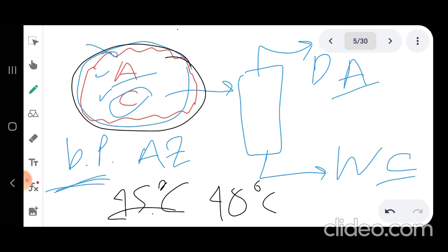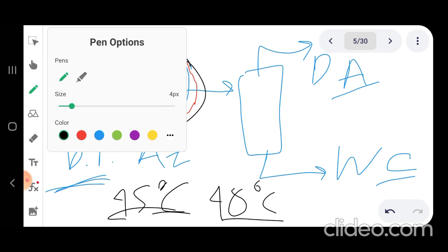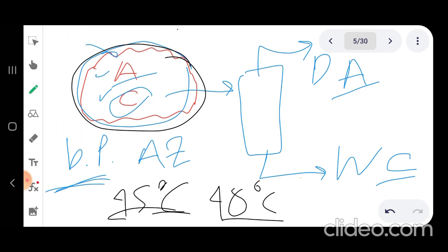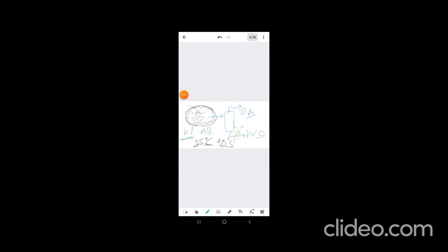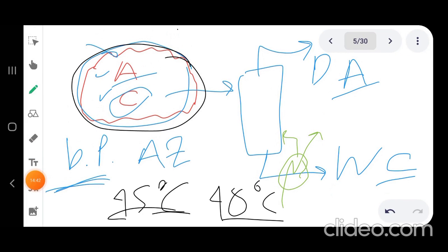These are very close, so separation by distillation looks to be not feasible. Another situation, another reason, for example, is, remember, in distillation we need what? We need a reboiler, where you heat and then get this oil up back to your column. As you know, this reboiler will increase the temperature.